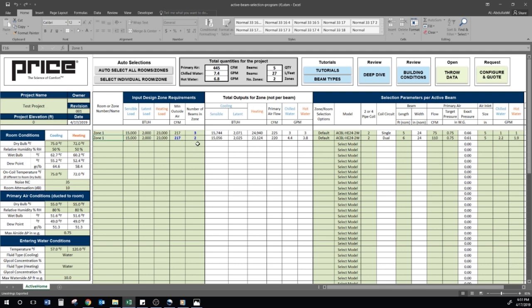For beam selections, it is good practice to decrease the CFM needed and put more of the emphasis on the water side. My auto selection should not be my final result. It is recommended to compare the selection to existing layouts and space geometry in order to make sure the selection makes sense. I can further fine-tune my selection as needed to better fit my application.